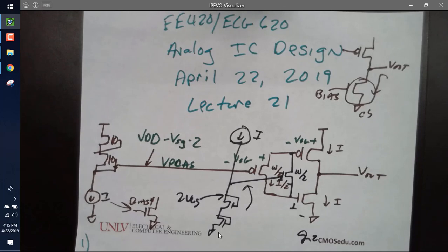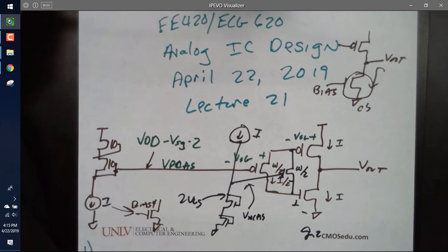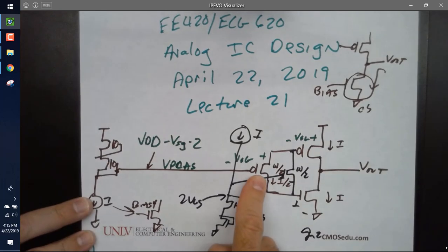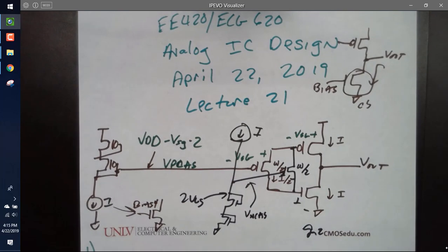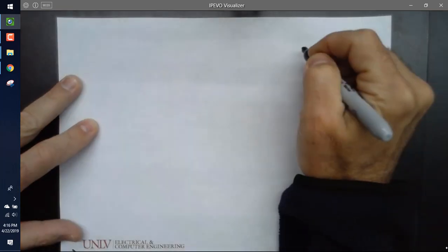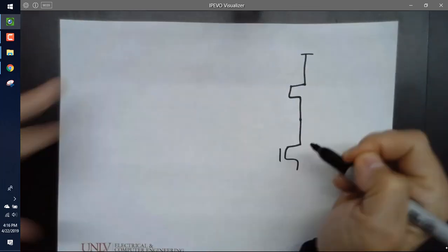All right, that's called VN CAS. Is that an NMOS in the middle of that? This is an NMOS, and this is a PMOS. I'm going to draw it neater on the next page. I just want to give you an idea for the biasing before I go any further. Okay, so I'm going to leave off that biasing for obvious reasons. It clutters up the schematic. And I'm going to sketch the push-pull output like this.